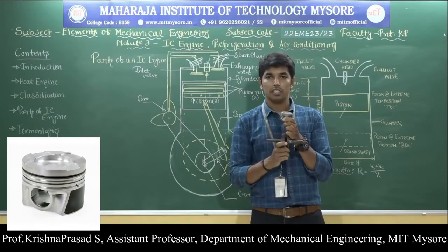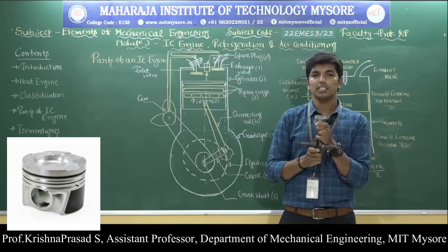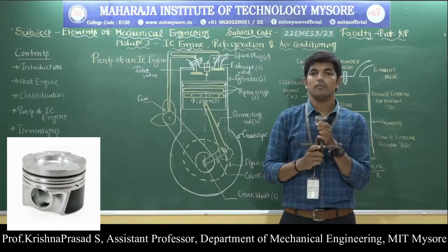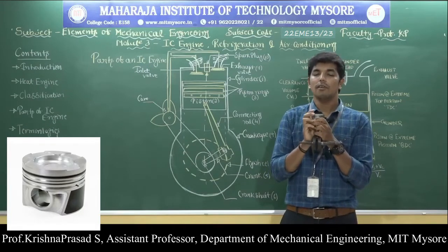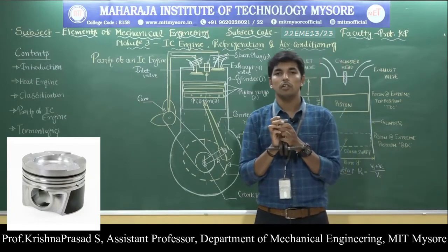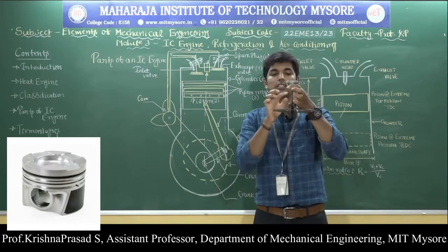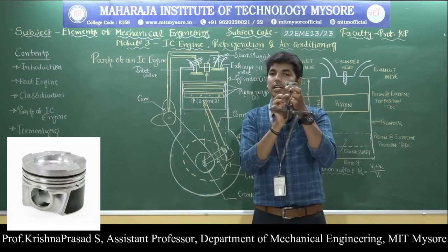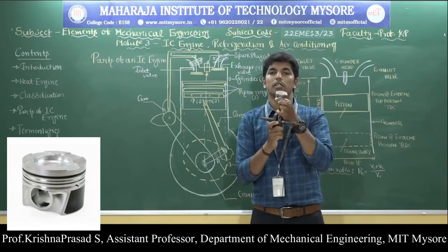And what is the main function of the piston? The piston is going to compress the charge. Charge is a mixture of air and fuel in the case of a petrol engine. It compresses the charge, and the power developed due to the combustion of the fuel is going to transfer from the piston to the crankshaft through intermediate mechanisms like the connecting rod as well as the crank. This is the main thing regarding the piston.